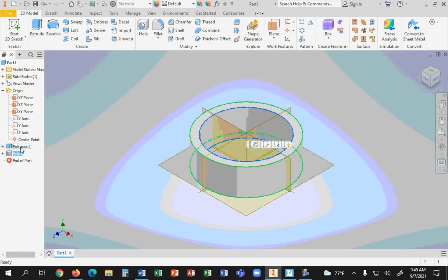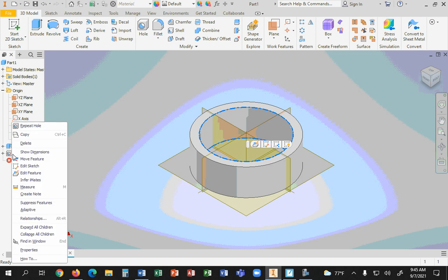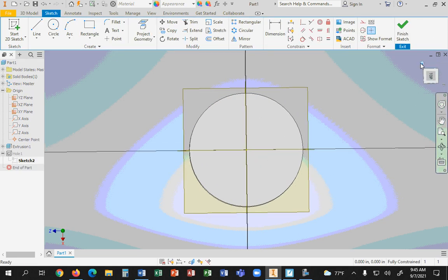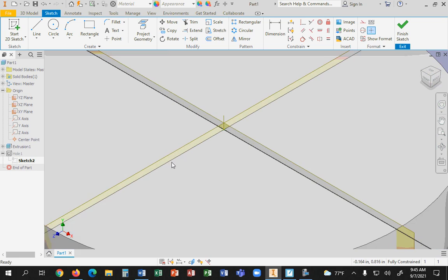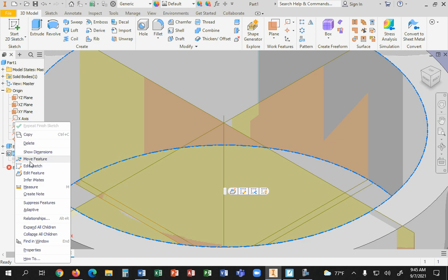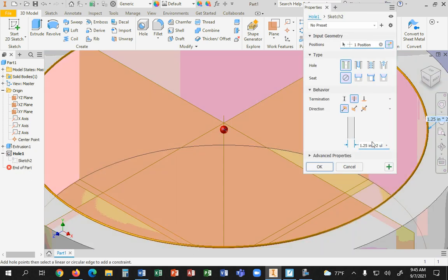Radius? Yes, good question. If after the fact I realize, you know what, I could just put the diameter, and why on earth did I do the math on radius? Right mouse button, you can edit that. Is it the sketch or the feature? Good question. The sketch makes the whole location. See that? And notice for the sketch, all you have is what? The dot. So it's not the sketch that I'm looking to edit. It's the feature. Because the feature contains all the content.